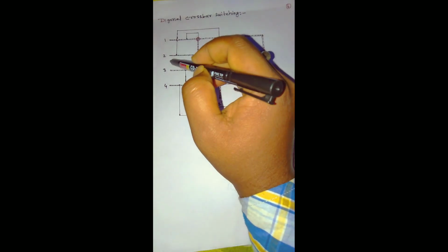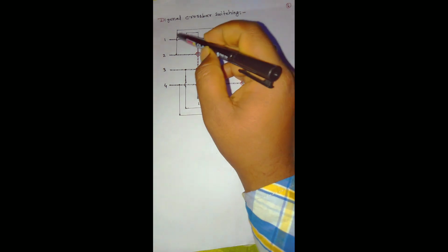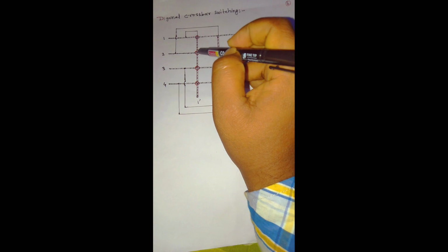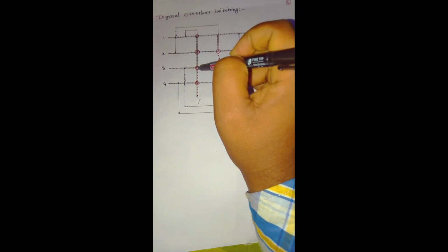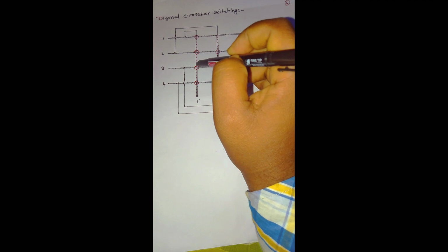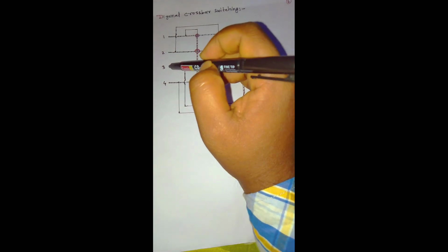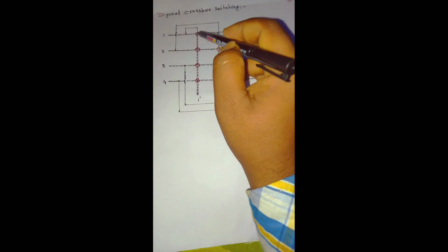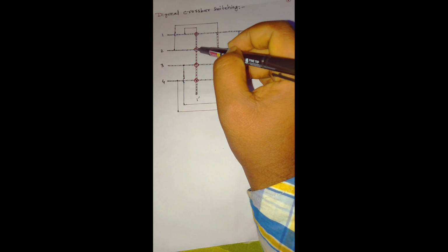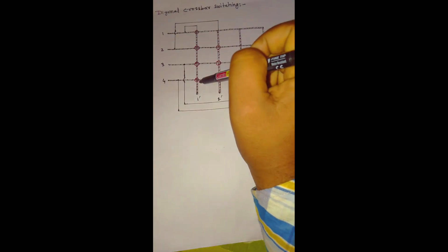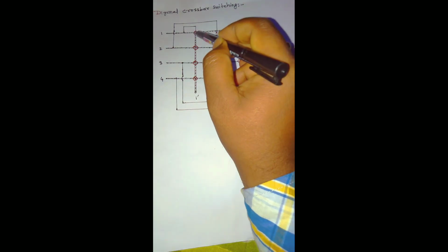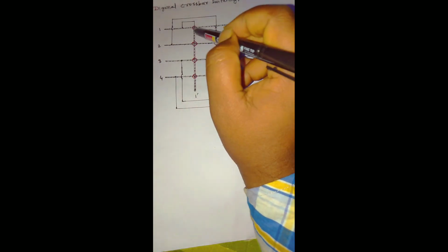Fine. If it is subscriber 3, that means subscriber 1 to subscriber 3, then this cross point, that cross point, not necessarily that cross point, this cross point and that cross point will get energized. So there will be some path between 1 and 3. If it is 1 and 4, then there will be this path. That means this point is energized now, and this point is now energized. So there will be some path between 1 to this cross point to that cross point to 4. So reverse communication is also possible.